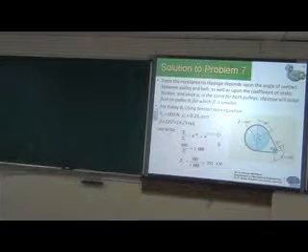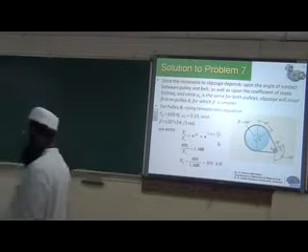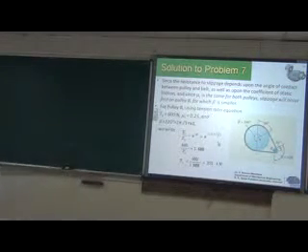So after that, you have to find out the torque. You have to take moment of all the forces for pulley A. You got tension, the same tension will be existing at pulley A also, on the same side. After finding the tensions, consider the system of forces, find out moment. e to the power mu theta, here beta, substitute for it. In general theta is put, but in the problem it is mentioned as beta.